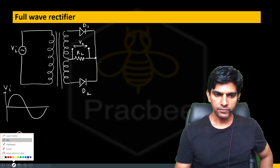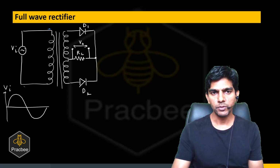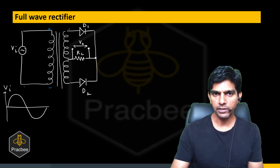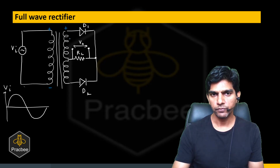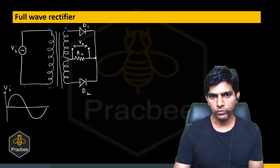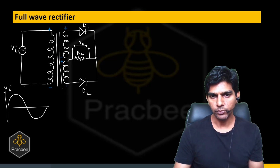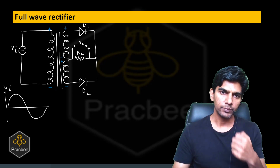In the positive half cycle, the top side of the primary will be at high potential and the bottom will be at low potential. Similarly, we can say the top side of the secondary will be at high potential. The secondary is made up of two parts. For the first part, the bottom side will be at low, and for the bottom half, the top will be at high and the bottom will be at low. So can you see what is happening here?